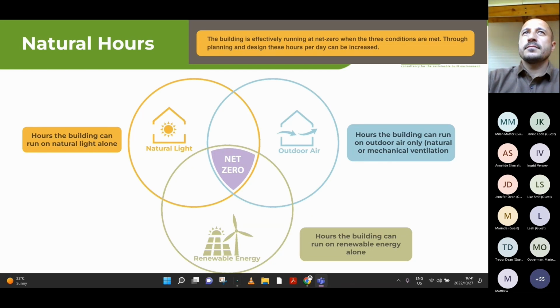So cost effective is always relative, right? Because people often don't do the right type of like for like comparisons. So for example, in a residential setting, you go to these high-end houses with lots of glass, and now they're air conditioning the spaces, which they primarily occupy at night. At night, this house is hot and you're running an air conditioner. If you had a heat recovery ventilator, you would have no air conditioning. You would just be using that to provide fresh air rather than normal cooling.